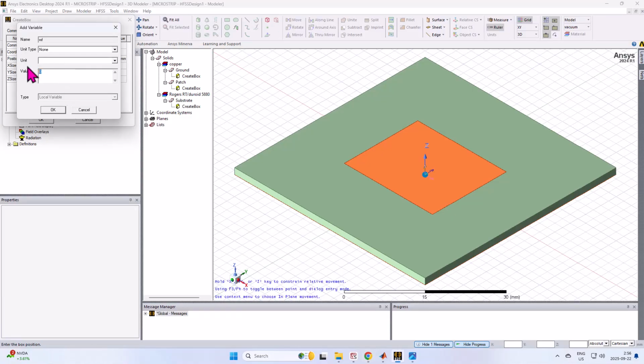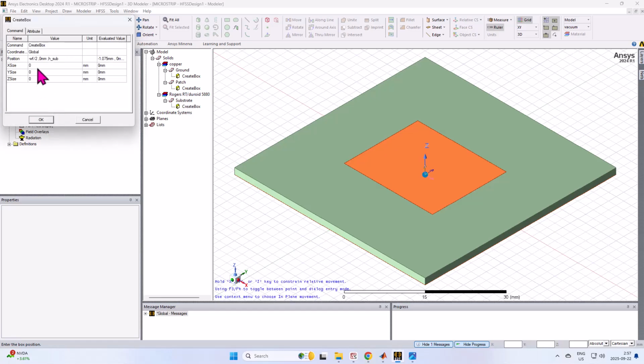So here, what is this? It is 2.15 millimeter. So I click on OK, and here again the width of that one is WF. So it will go from 0 exactly till here. Okay, so the whole size was WG, and it will go from 0 to minus WG over 2.